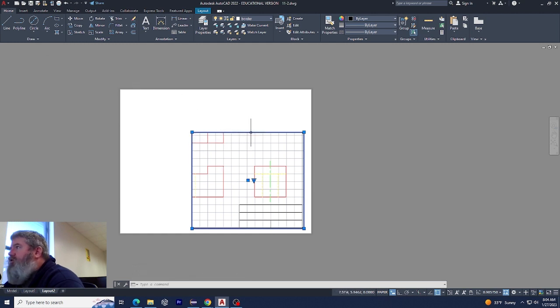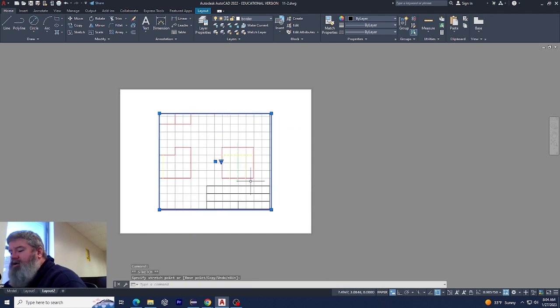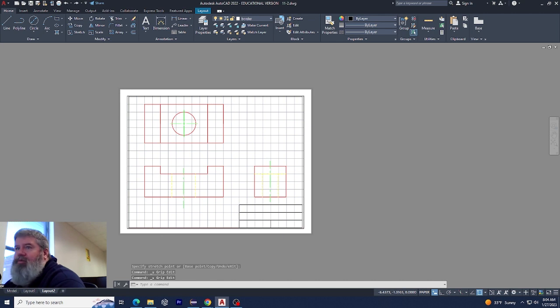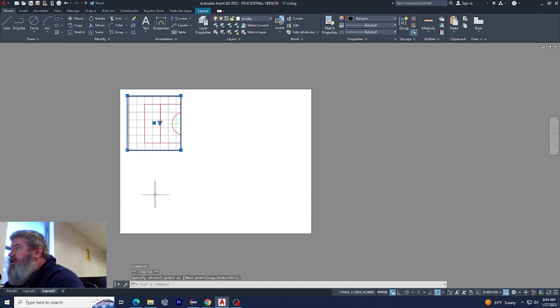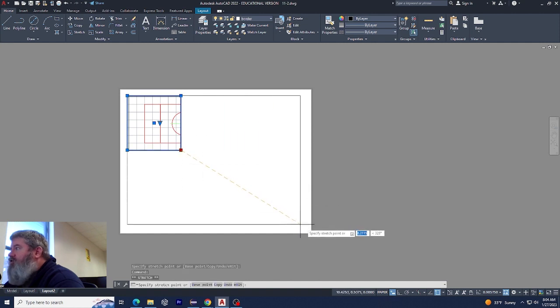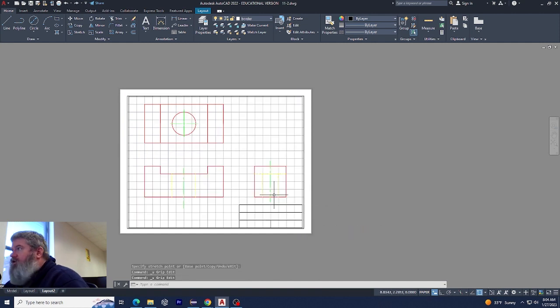I can add points in it using the polyline command and reshape it. I can move it around. Anything you want to do, you can do to that viewport. If I want to just show part of it, I can move it around. So viewports can be reshaped, resized, and put anywhere you want. So if you do just one, and you decide you want 3, you don't have to delete all this and start over. You can just shrink this down to the size you want it. And, you know, you could put it, say, right up here. Then you could add another one here and another one here. So you can have as many as you want on there just by drawing them yourself. Why don't I do that instead of undoing? Okay.